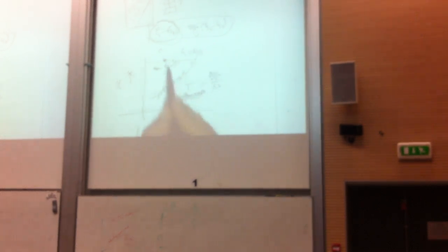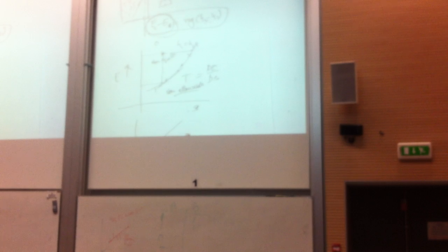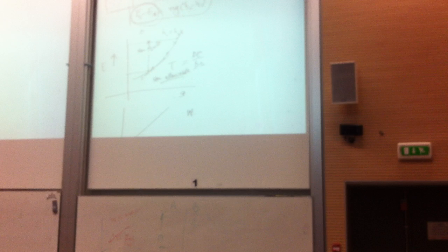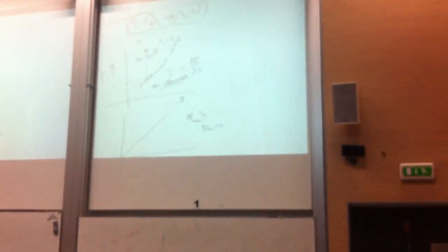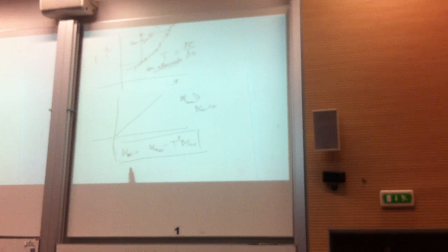Okay? We can do another thing, that you can interact with this. Come straight down. If you come straight down, it means that this is the most efficient way of doing work. So we will say W max. You will get W max when, I'm not deriving all those relations because I don't have time. So I'm just revising things that you need to learn and remember all the time when you are solving these problems. W max will be possible when dS_irr is 0. If no entropy is generated, W max is what you get. So what is the relation between W max and W actual? You will see the derivation. W actual, or W output, is W max minus the temperature of the reservoir times dS_irr. This is the relation.